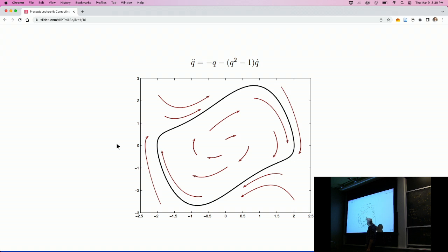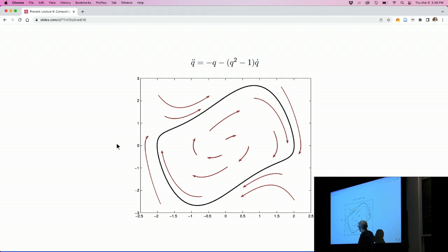It happens that there's a fixed point at the origin, but everything else goes out until it comes and goes into this stable limit cycle. We'll actually study this again when we talk about limit cycles for walking robots and the like, okay? But it turns out the dynamics of this will converge to that black orbit. And from the outside, it actually converges in. It's a stable nonlinear oscillator. It turns out to be a great example for region of attraction analysis because, well, what's the region of attraction? It's just the point, or you have to think about the region of attraction of a limit cycle, which we will do. But what I'm going to do right now is reverse time.